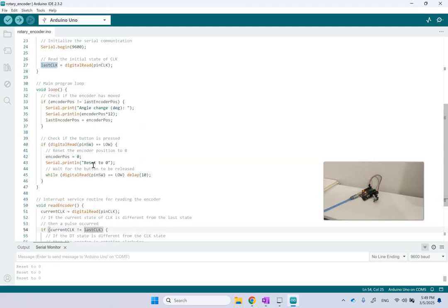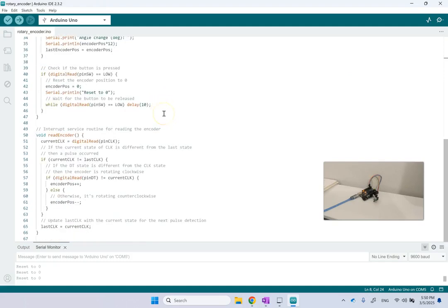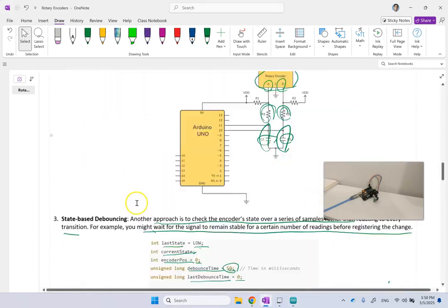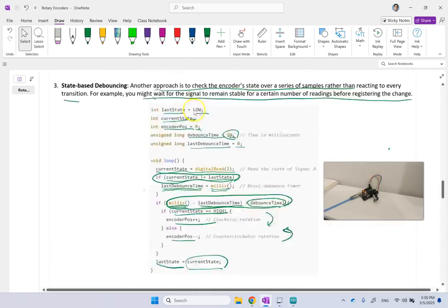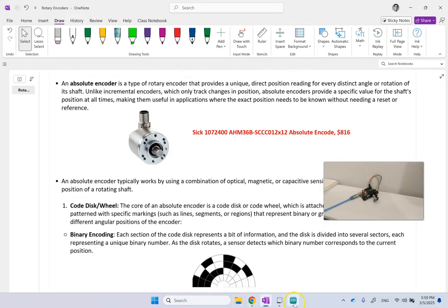So you see that here, basically we are using interrupt and checking on the state. We are not using a delay for reading, so the debouncing is not necessarily used here because I'm really being very slow by rotating it. But if you want to go fast and there is a better chance of bouncing, it is really a good idea to put one of those 2 different methods that I showed you inside your code to do the debouncing, especially this one, which has a simple delay-based mechanism.